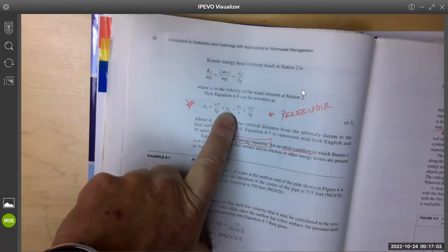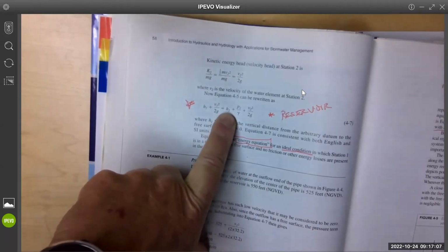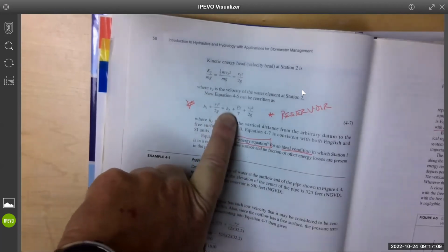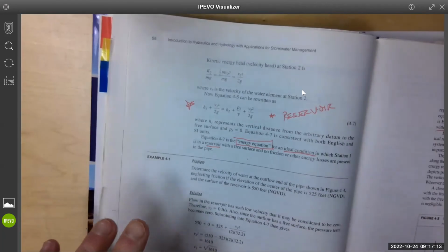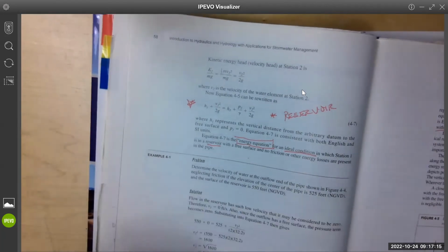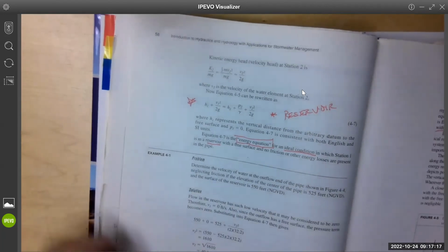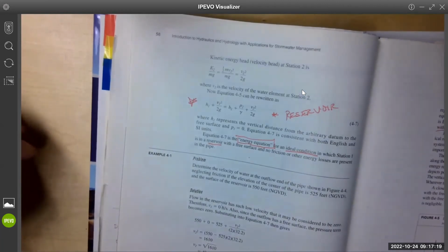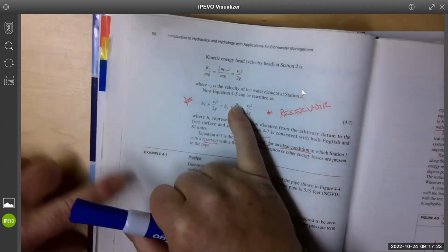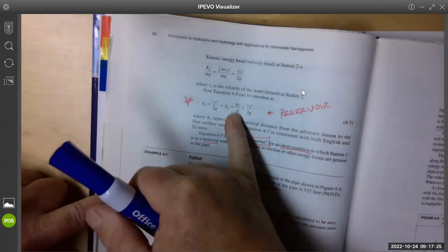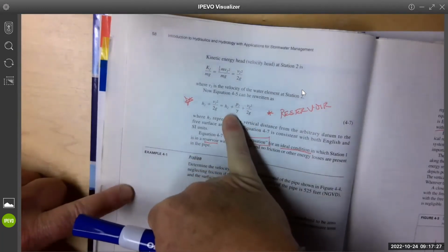Is it just V1 that's velocity head, or is that whole number? No, it's the whole number for sure. V1 is velocity. So V is still just velocity. Gotcha. The head is the whole equation. Same with this one, right? P is still pressure, but pressure head is divided by the specific weight of the fluid.